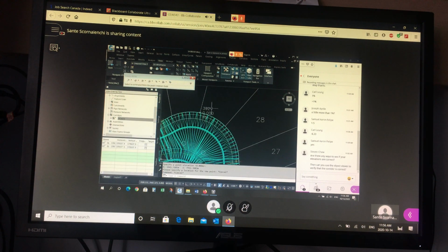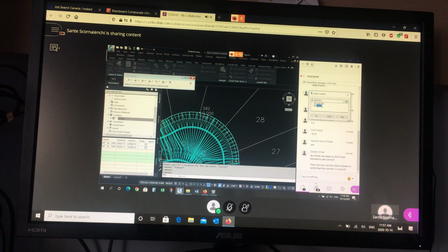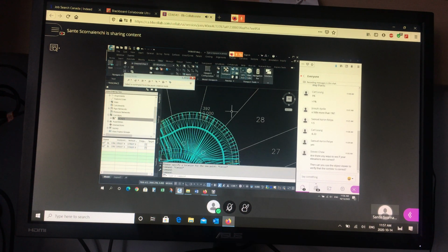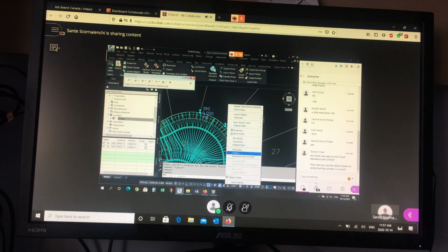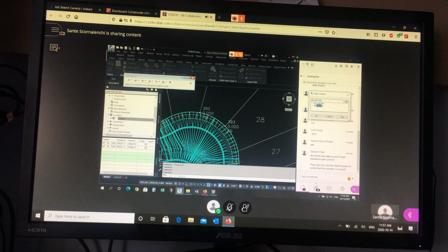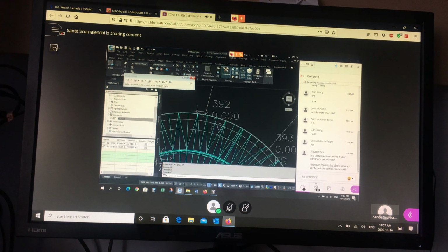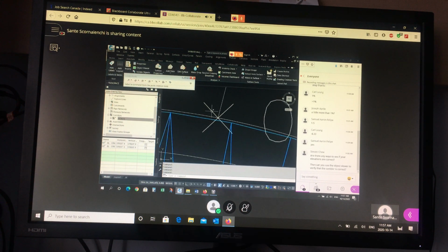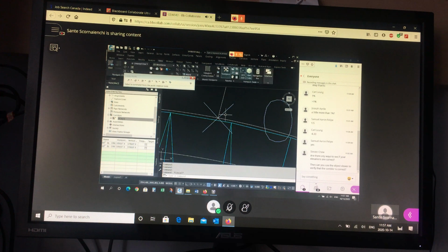If I click on there, and I say right-click, elevations from surface, and I want the corridor elevation, watch what happens. Nothing. See how it's still 0? If I put a point here, end point, and I click on that, you can select more than one, elevation from surface, get it from the road surface, they're 0. They don't change. Why? If you zoom in, you'll see the surface ends here, this point is out of the range. So if there's no surface where the point is, it's not going to get an elevation.